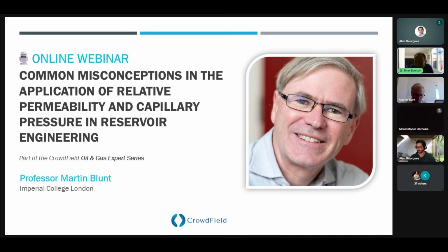I think you answered a bit of the previous question. What took my attention on the outline was that gas can be wetting the water. Yes, and I explained it by the CO2 and three-phase situation, but any further comments? Because we have done reservoir conditions water injection in gas reservoirs, steady state, unsteady state, and so on. And surprisingly often, we do see an end effect, meaning, can we see gas wet? Which is, to me, unexpected in most cases.